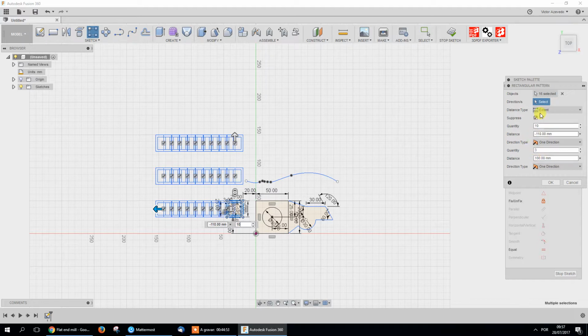You can also define extend, or the value you put here, the distance, is divided by the number of features you added, or you can place spacing, and that defines the space between each object. Okay, you can later try.